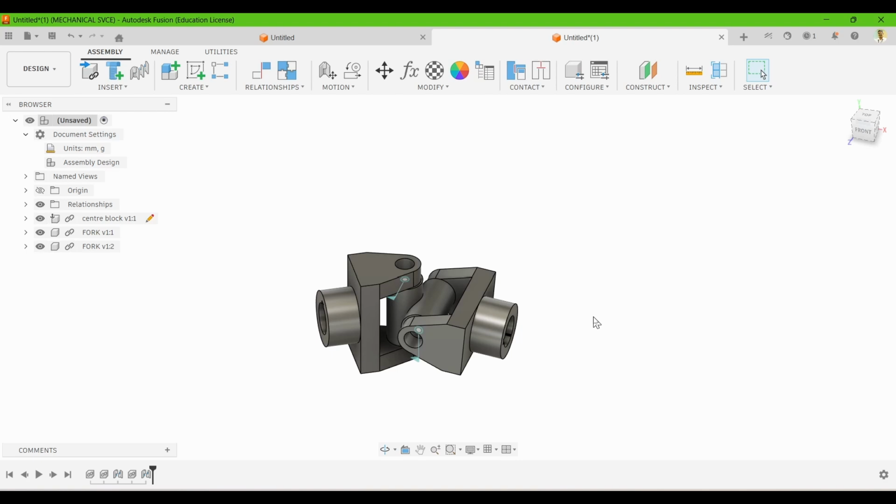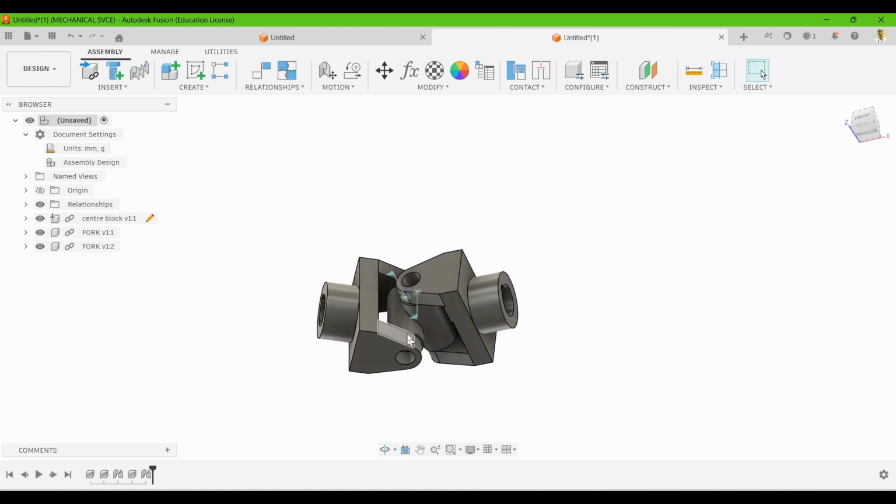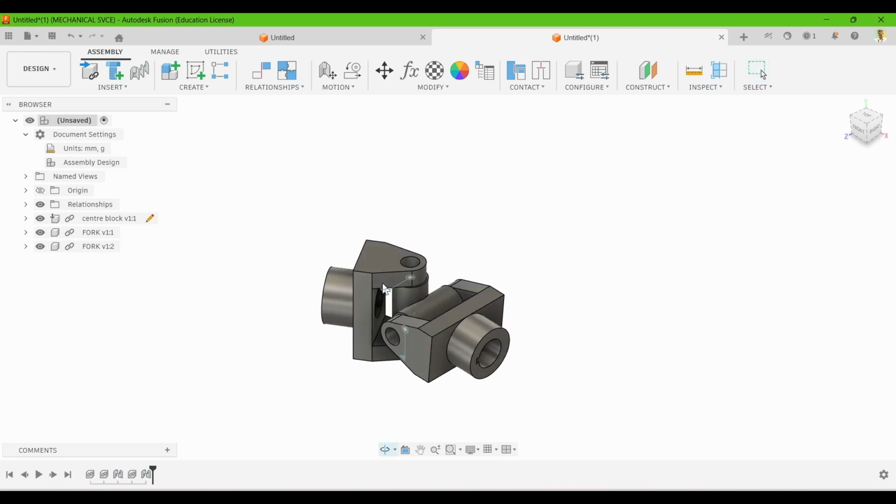What is this used for? Sometimes for analysis, for this kind of joint related analysis, you can use it. The other things are direct connections. What are we going to do next? A pin. You have to insert one pin here. On top, put a collar and then a taper pin. This is the way you are going to assemble it.